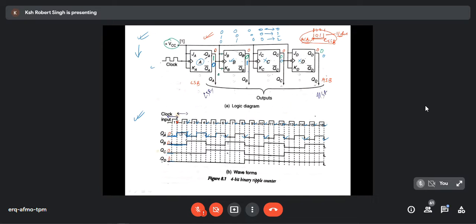The trigger has not come. Yeah, now the trigger has come. Now it will toggle. Output will change from 0 to 1, and it will remain in 1 till another pulse comes. Yes, another edge, so it will toggle. It will go down and remain low till another comes, and it will go high, low, high, low. It will go like that.